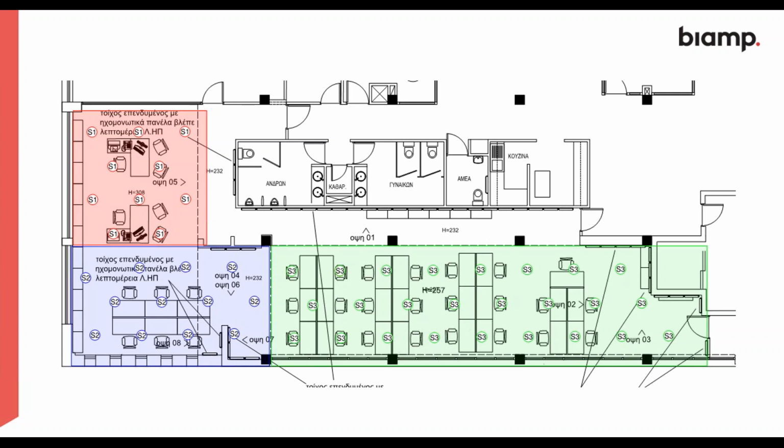Does the masking affect web conference microphones? It should not affect web conference microphones if they're a decent microphone. If you have omnidirectional microphones stuck on the ceiling, and it's a high ceiling, then theoretically they will hear the masking. In those applications, we would use a room controller to mute it. But if we use a proper microphone, then no, it shouldn't.